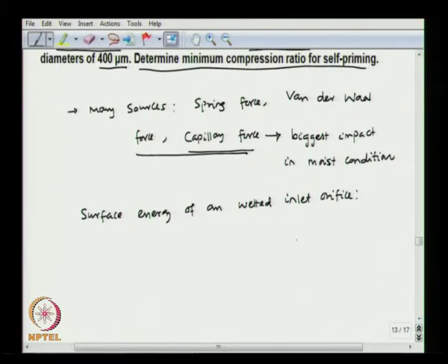Okay. So, you have a valve port something like this, and here, let us say, the valve seat. So, you have this tiny gap between the valve seat and the valve actuator. Okay. So, this gap, let us say z. In moist condition, when this is handling liquid, you would have a liquid film sitting here.